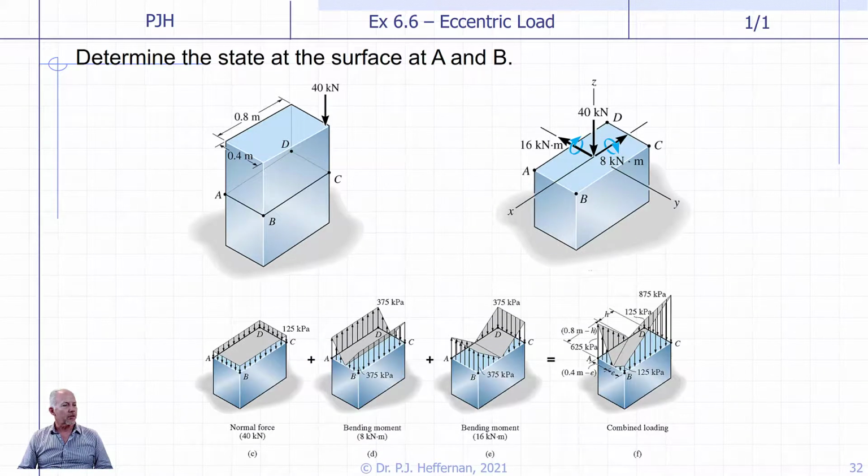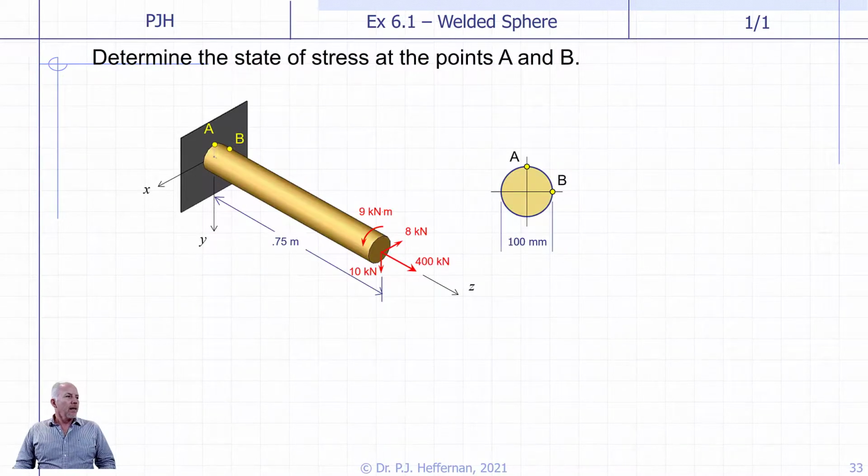And this just shows you what it's all going to look like when you go through it and you break it up into its components. But again, if you go through the solution, you'll see that. Then we have a few more examples where we just look at complex loading conditions, break it up into its parts, get the stress at a point or points to be considered, and then as you can see, it would make sense to go on and do the principal stresses in those cases.